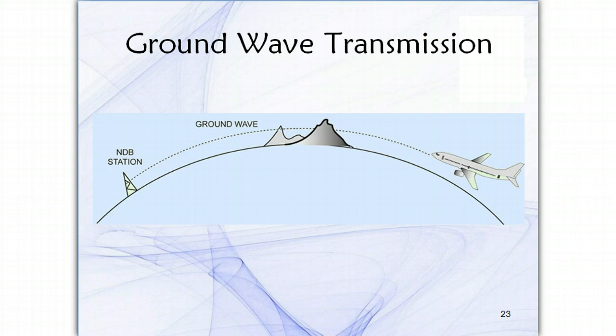They produce steady communications and navigation because the signals are not blocked by the horizon. They have many limitations, though, including great susceptibility to electrical interference, natural and man-made. There are few channels and a lack of global range. The services now on low frequencies are ADF, Automatic Direction Finder, LORAN, and until recently Omega, which has been decommissioned because it was much too expensive to run.